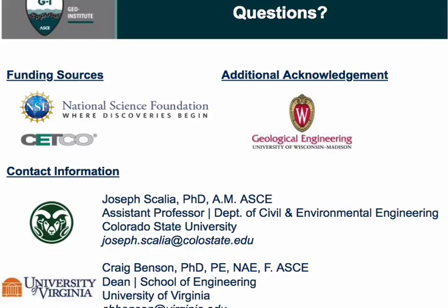So it's not a cut and dry answer there. Really, a hydraulic conductivity test is needed to ensure that there's compatibility between the permeant solution and the GCL. And that permeant solution needs to be tested with the specific GCL that's going to be used in the field, with the effective stress that's going to occur in the field, really to make sure that under the site-specific field conditions, you're going to have a low hydraulic conductivity. And so a blanket recommendation, get it wet, keep it wet, is probably an oversimplification. There needs to be assurance that site-specific tests are conducted and that those site-specific tests provide a low hydraulic conductivity.